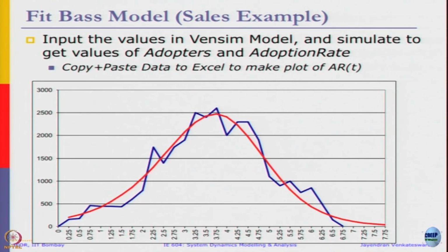So to get this graph, we have to copy paste the data from Vensim. You need to plug the data into Vensim, simulate it, copy the data, paste it back in Excel, and then do this. There are ways in which we can get the input data itself, the original sales data, the blue line that you see here, into Vensim, but I will show that later.